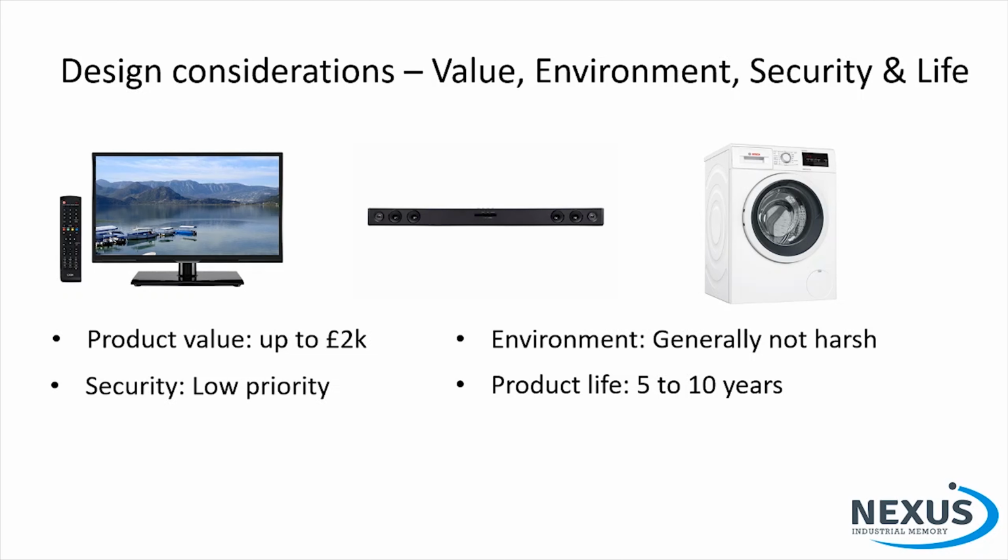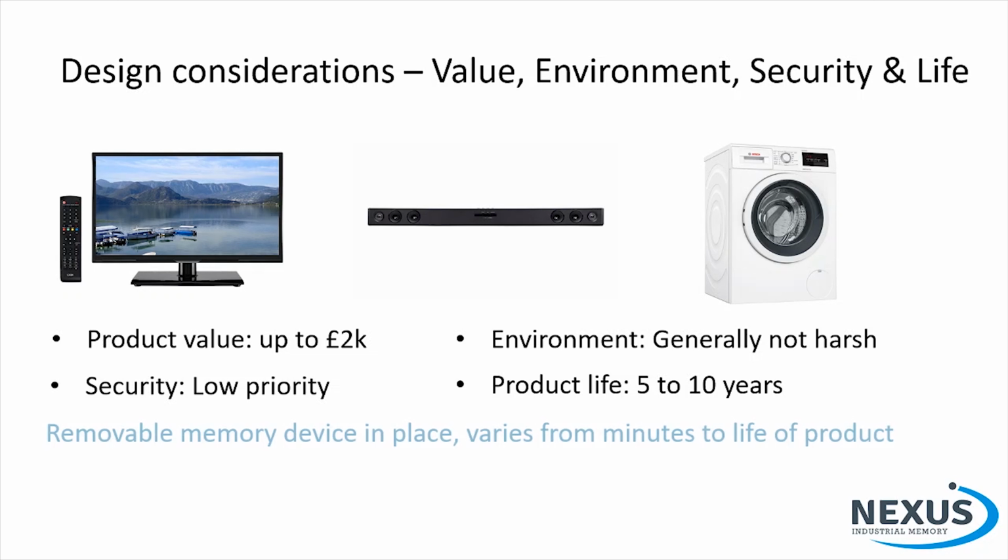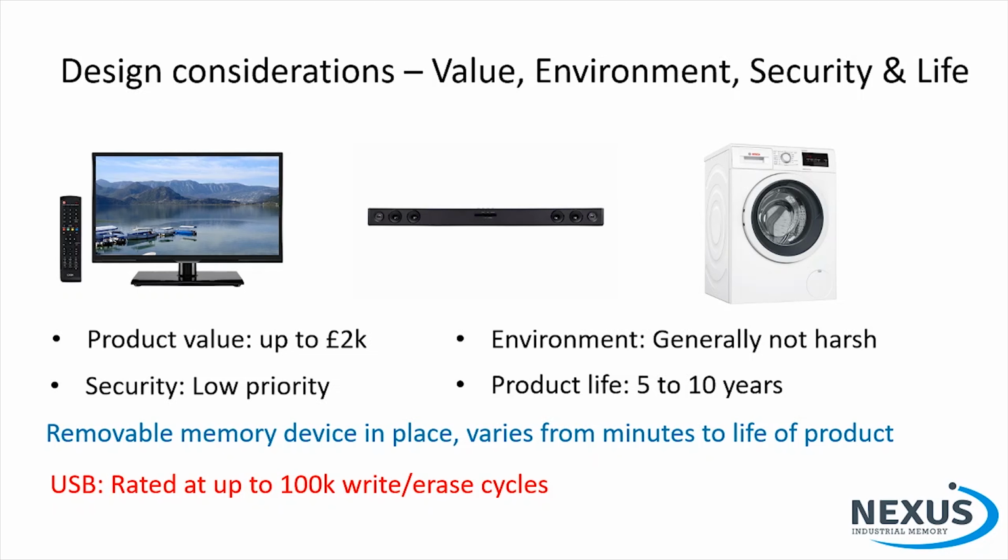The frequency with which the memory device is inserted and removed, and how long it is in place for, will vary depending on the application. This needs to be a design consideration because there are limits to how many write and erase cycles you can expect from a removable memory device, and they will have a rated number of insertions and removals. These considerations apply to all other applications discussed in this presentation, but won't be repeated.